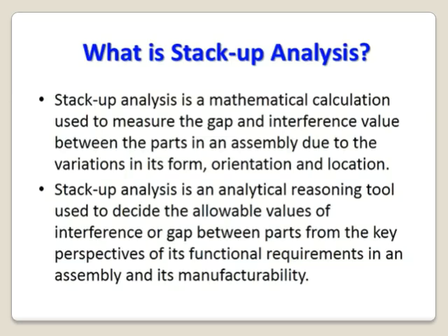Coming to what tolerance stack-up analysis means, as a definition: tolerance stack-up analysis is a mathematical calculation used to measure the gap and interference value between the parts in an assembly due to variation in the form, orientation, and location.